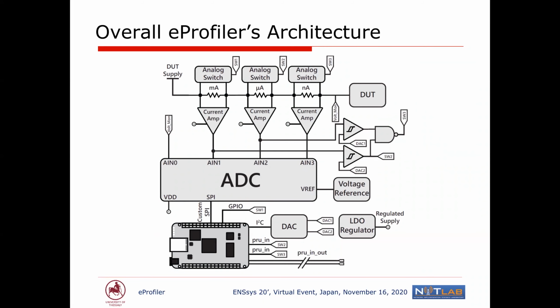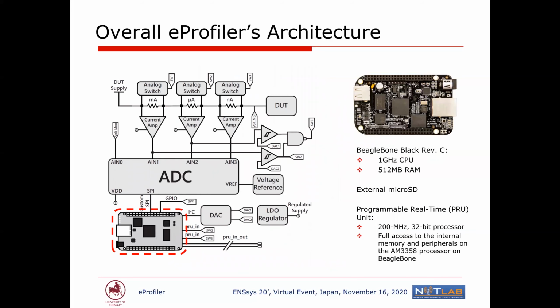The overall architecture we followed is presented in this figure. A dynamic shunt resistor switch that supports 3 different ranges is implemented featuring a 1 ohm, a 100 ohm, and a 10k ohm resistors. The embedded PC we opted for is the Linux-based BeagleBone board, which is a low-cost embedded platform characterized by sufficient processing power capabilities, low power consumption, and several communication interfaces.